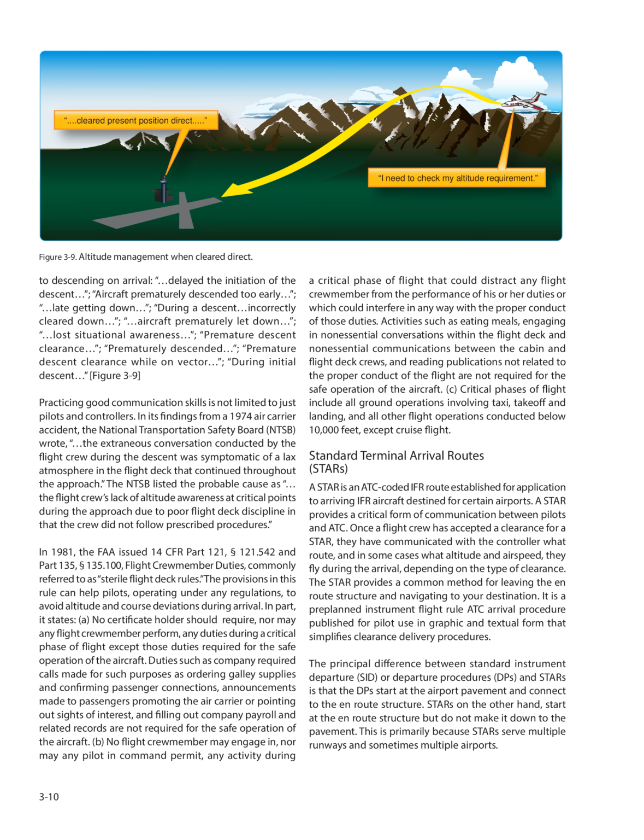Activities such as eating meals, engaging in non-essential conversations within the flight deck and non-essential communications between the cabin and flight deck crews, and reading publications not related to the proper conduct of the flight are not required for the safe operation of the aircraft. Critical phases of flight include all ground operations involving taxi, takeoff and landing, and all other flight operations conducted below 10,000 feet, except cruise flight.